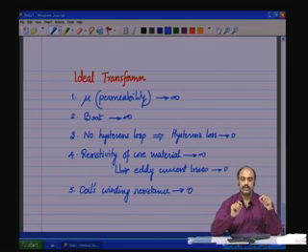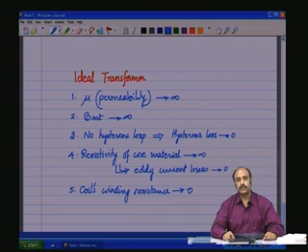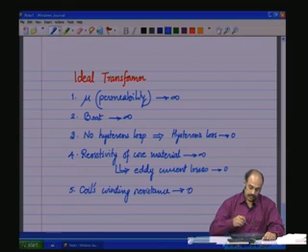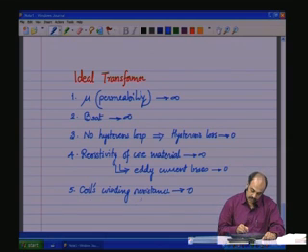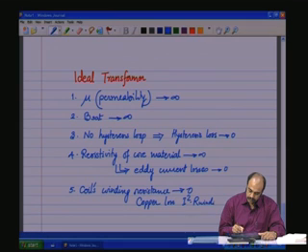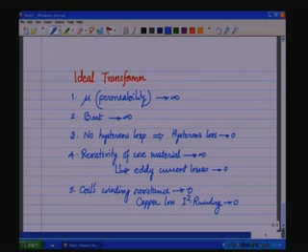So, therefore, if there is a winding of finite number of turns, the resistance is also finite, and therefore, there is going to be I square R loss. So, if the coil's winding resistance is tending to 0, there is no copper loss. The copper loss, I square into R winding, will also tend to 0. This would be an ideal transformer with absolutely no loss.